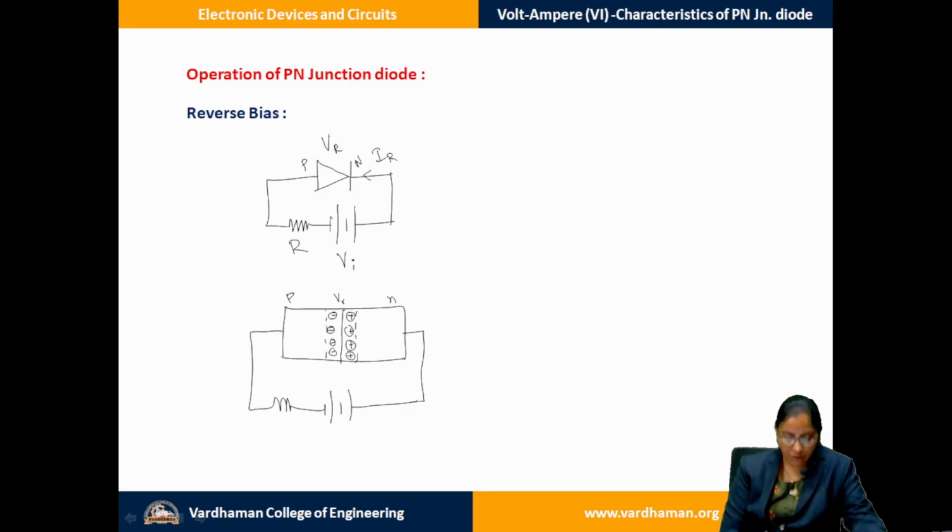So here when we keenly observe, as we vary our input voltage, a reverse bias, what is the change that happens to the PN junction diode? Let us observe. As we have connected the negative terminal of the battery to P material, the ions cannot be nullified because of the negative potential, but the ions which are present in the other area of P, which are not part of the depletion layer, will experience a repulsion force from the negative terminal, because of which more and more ions tend to get accommodated towards your junction.